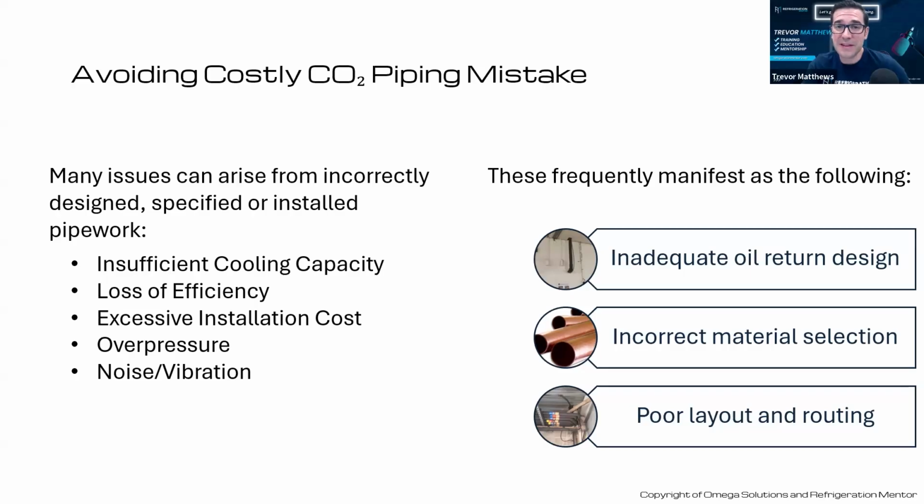The big thing is that, when I worked on lots of construction jobs, we would just grab pipes and pull them in and start putting them in. But I've heard of stores where they put all K copper on the high side, and that is something you cannot do. And as a designer, you need to make sure when you're drawing this out that you label it correctly after you do the design, so that they understand what you need to put in there.